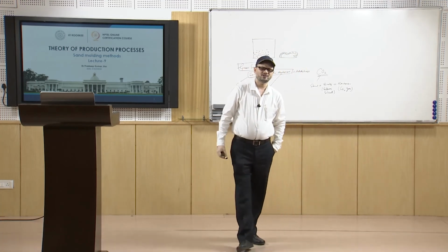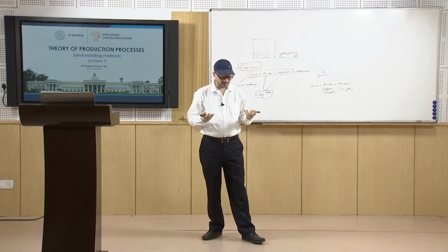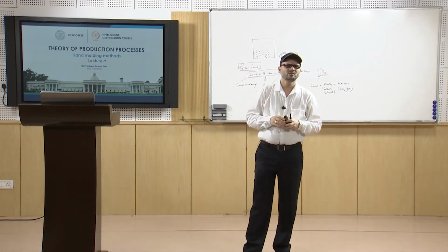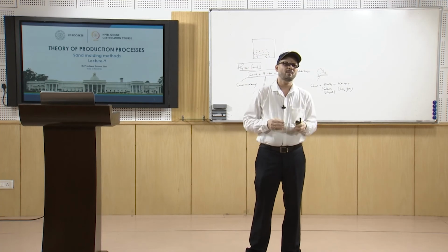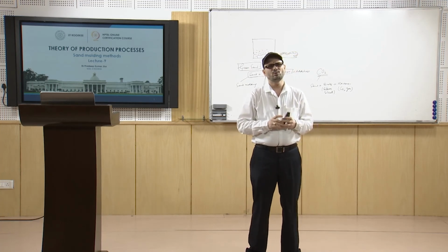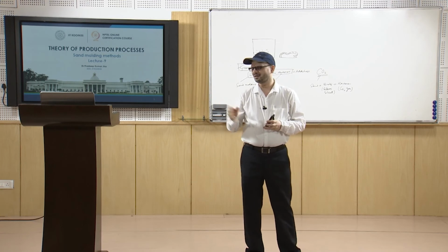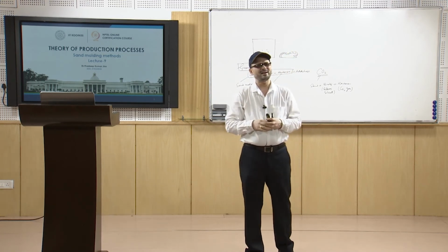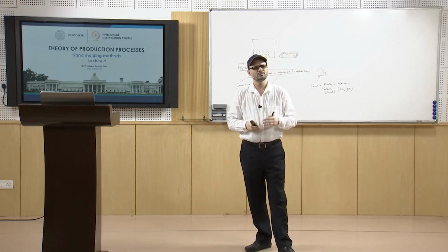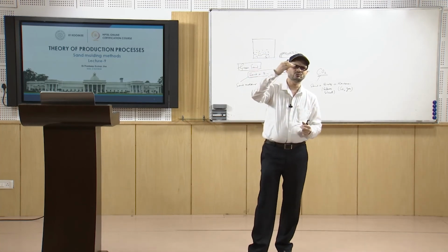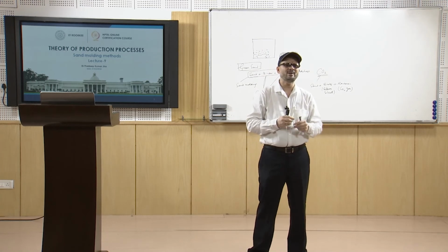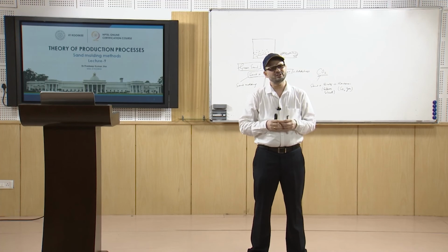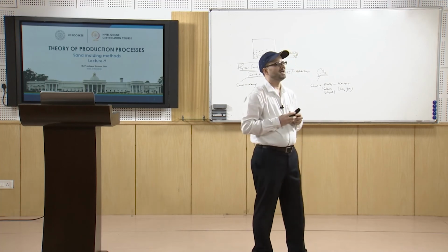Molding process equipment: when we make the molds we use different types of molding process equipment, especially for ramming. As we discussed, when we have very small molding, we use the hand rammer, but in case of machine molding, for ramming you have machines like the squeezing machine, jolt and squeeze machine, and slingers.